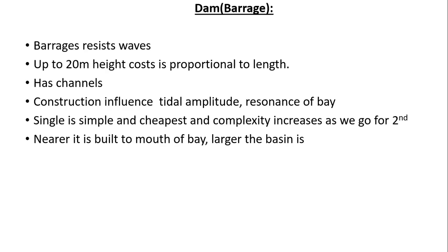Okay, next, flatness. Flatness is required for the sea bottom because sandy bottoms usually necessitate piling. Where sand or rock can bear the weight of the structure to be implanted, the bottom can be prepared and the structure placed on it and then secured. Prefabricated concrete blocks are used as the core for larger barriers, and this avoids filling with rocks and concrete.